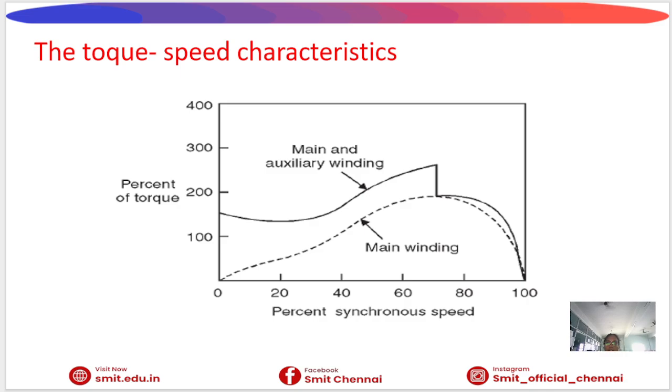Torque and speed characteristics show zero torque at standstill. Torque increases after starting, with maximum torque below the synchronous speed. The motor always runs at a speed slightly less than the synchronous speed. Slip speed is the difference between these two speeds, the synchronous speed and the rotor speed.